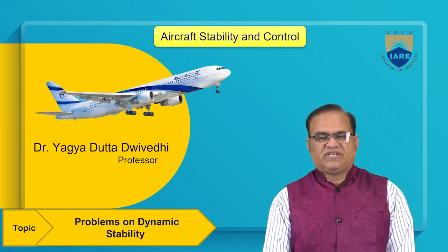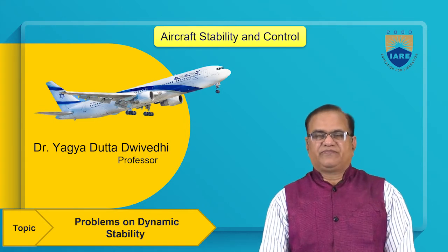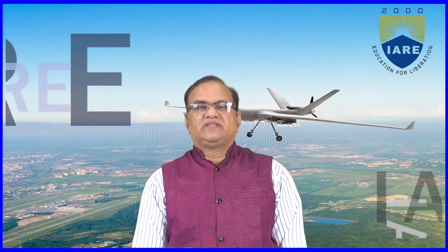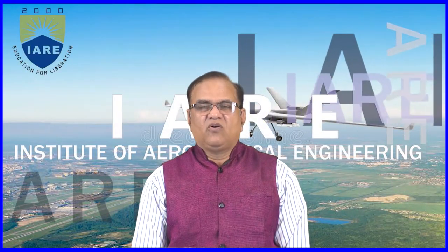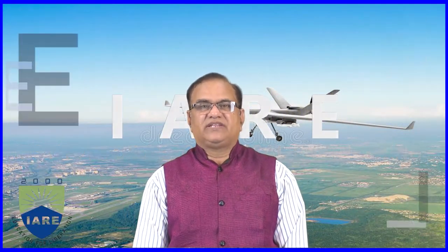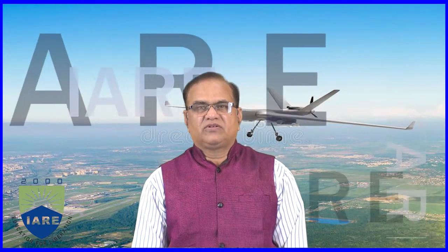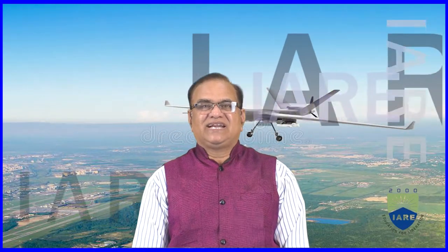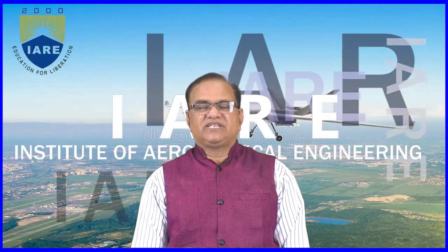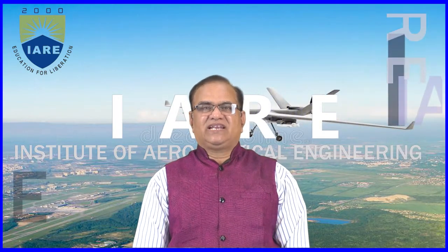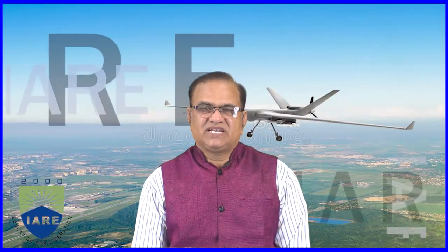We should first understand what static stability is. Static stability is the ability of the aircraft, once it is disturbed and the disturbing force is removed, to tend towards its equilibrium condition. If this condition is met, we can say that the aircraft is statically stable.